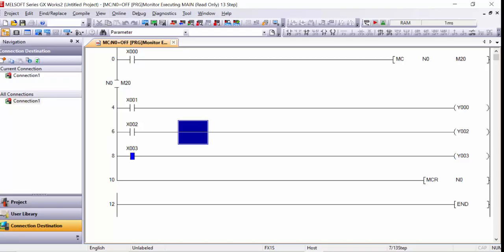And for example, if you remove the signal of X0, your output will immediately stop, because this signal may be an emergency, or however you design this logic in the program. As you remove the signal X0, your complete program will be stopped. And as the signal comes again, your output will be energized. If your signal continues, your program will execute, and your output will also execute. If there is no input, only the main is on.